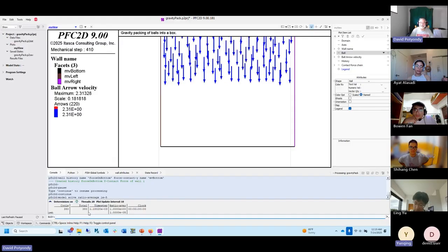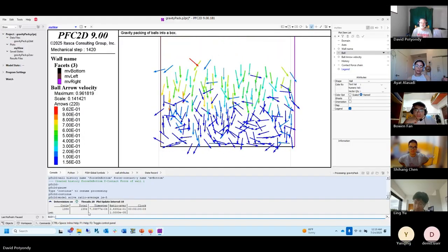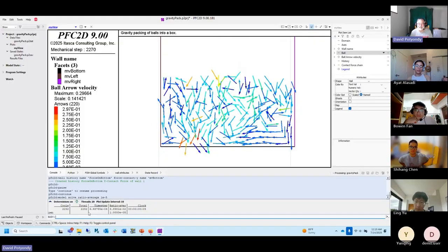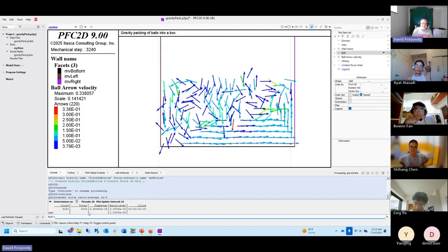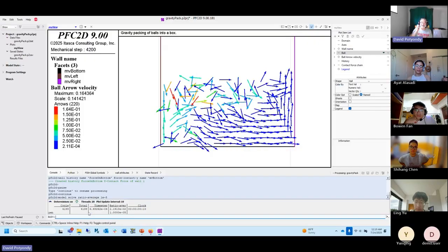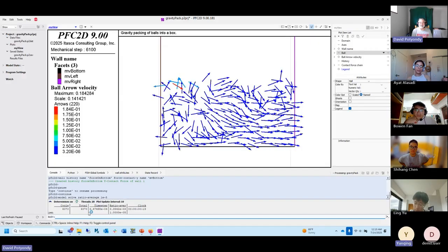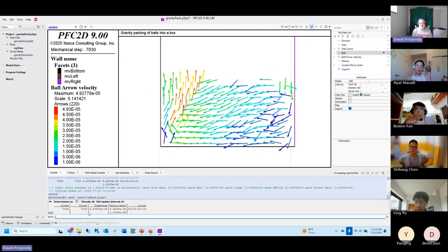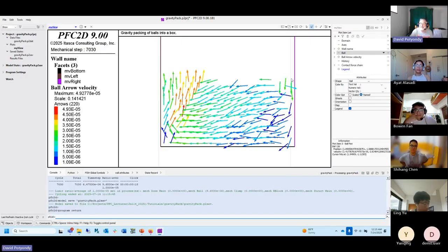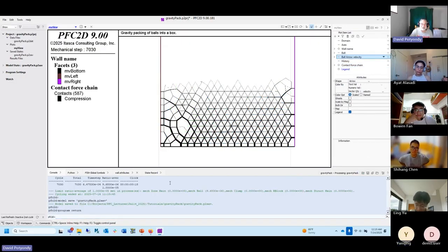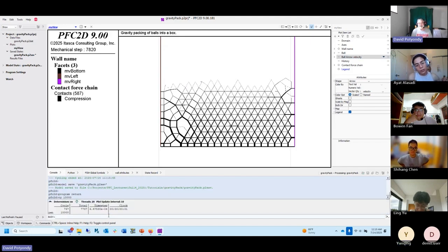and we'll look at the velocities. Super cool. You're going to watch it rearrange. You can see it vibrating, those velocity vectors are zipping back and forth. And as it starts to get to more equilibrium, now it's this sort of coherent pattern of moving around. Again, if we look at the force chains, which is really what we care about, now we can continue for a long time. Look, the force chains are not changing anymore. This is very low level vibration, sort of coherent motion going on.